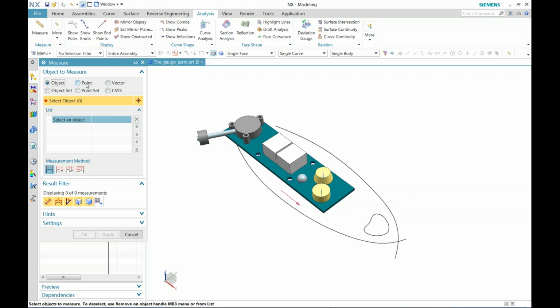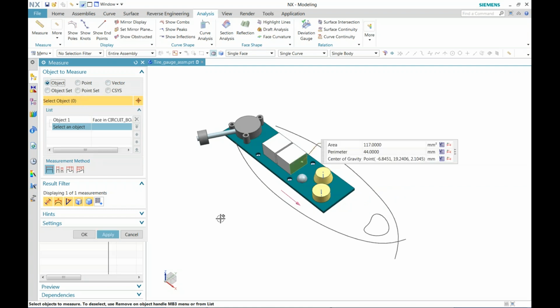If we do select something, what we can do then is start to tell you the properties of it. If I select that planar face there in the middle, you'll see this dialog come up that tells us the area, the perimeter, and the CG. We're going to change this to the centroid of that particular face. And we can choose now, if we want to save one of those as an associative feature, we can do that, right? We can click the little save button here to save one or more of these as an associative feature. I'll grab all 3 of these just for fun.